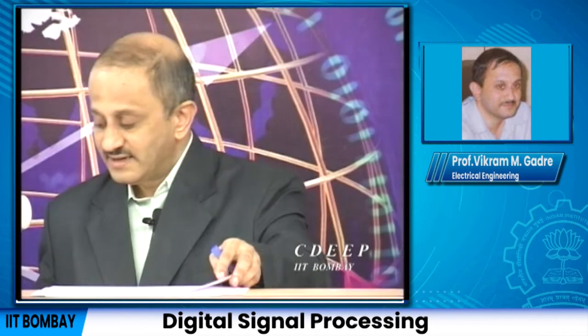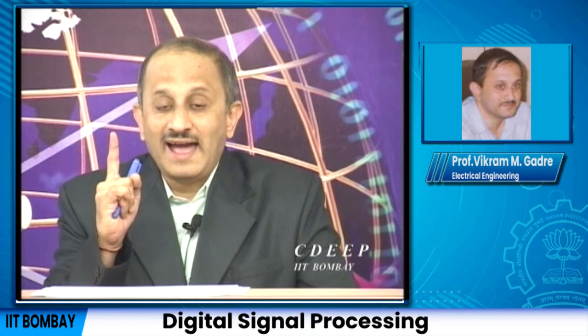Now, you see what we have here is what we wanted, except for the factor of half z inverse in the numerator. Now, having a half is not a problem. You can remove the half, the z transform is a linear operator, so that is not a problem. You can just remove the half by multiplying by 2. What do you do about a z inverse?